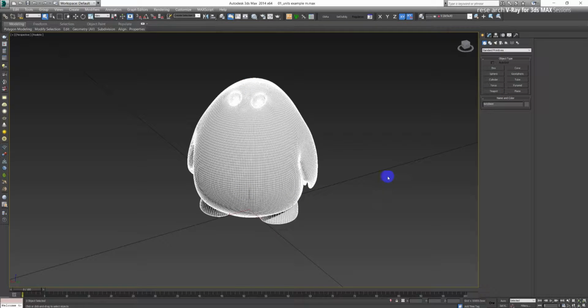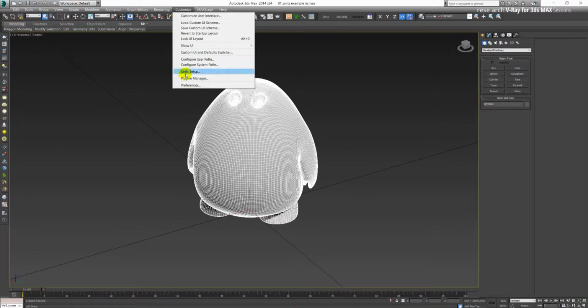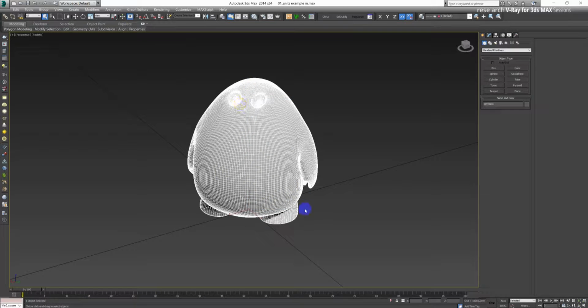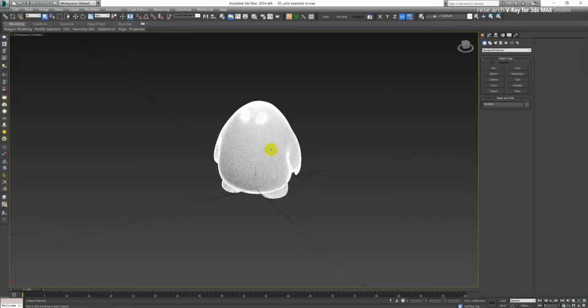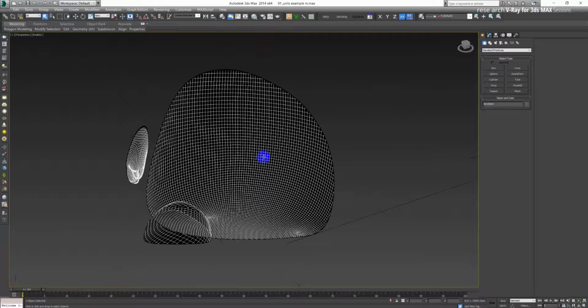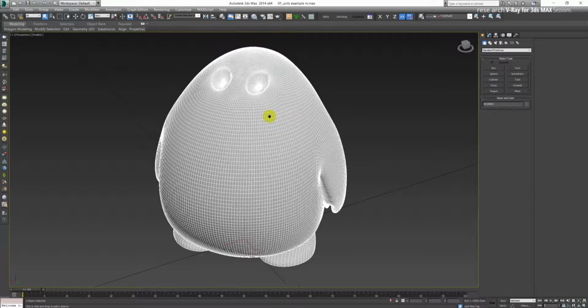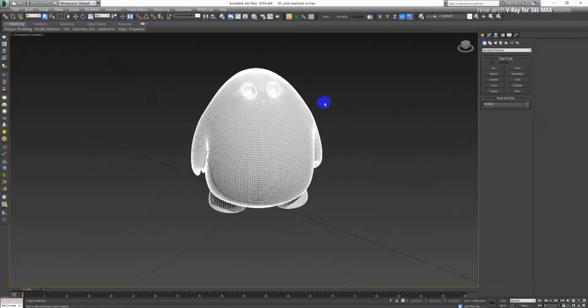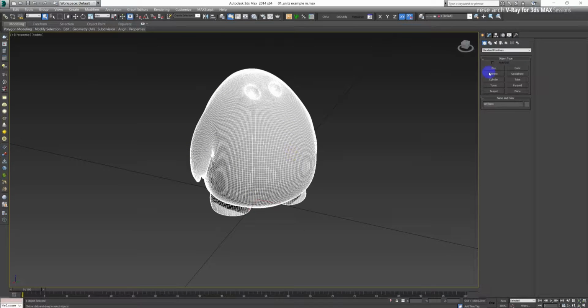That means that when I have my scene set to meters, this is not even 1 unit size, right? It's like half of the unit. So this is why the step is also bigger. Meters are not dedicated for this type of detail, but for much bigger scales and scenes.